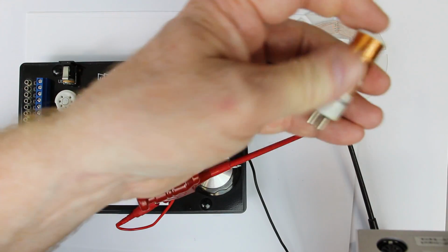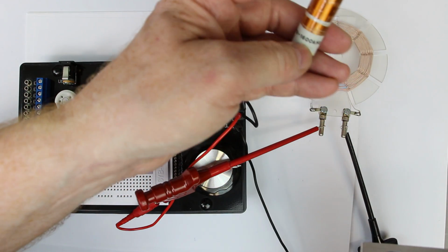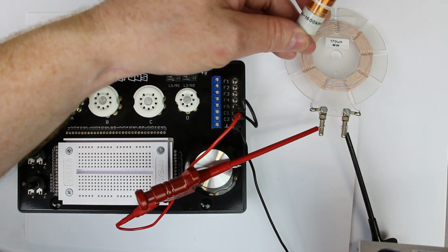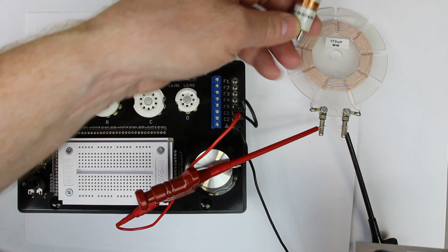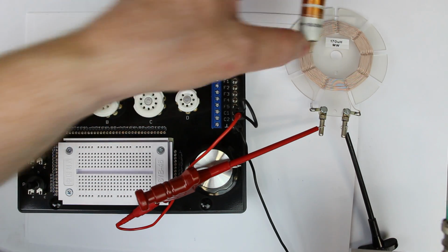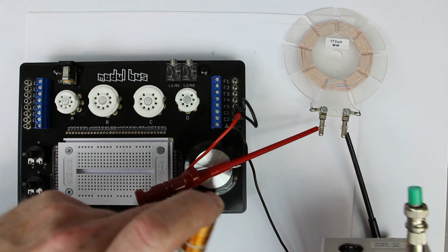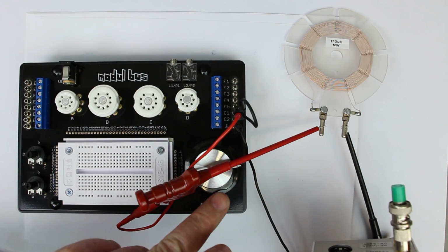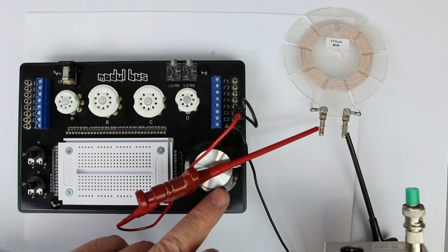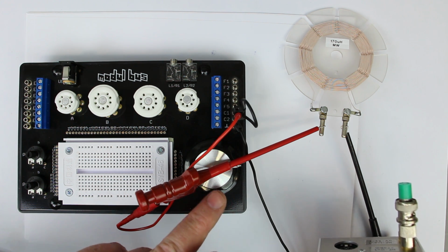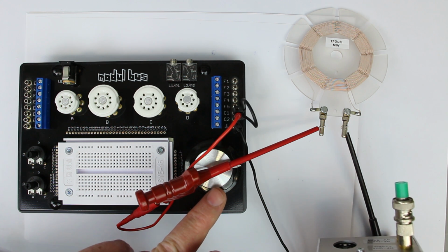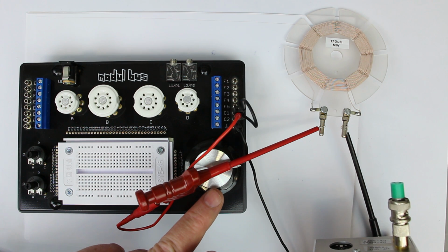The reason is with this coil I can only go up to 1.6 megahertz or 1600 kilohertz, as you can read, from 800 kilohertz to 1600. That was the reason why we couldn't exactly reach the endpoint, but we can be quite sure that we can reach at least 1.7 megahertz or 1700 kilohertz, and this is the upper end of the AM band, even in the United States.